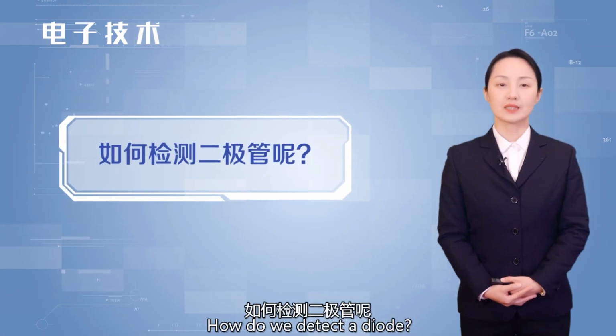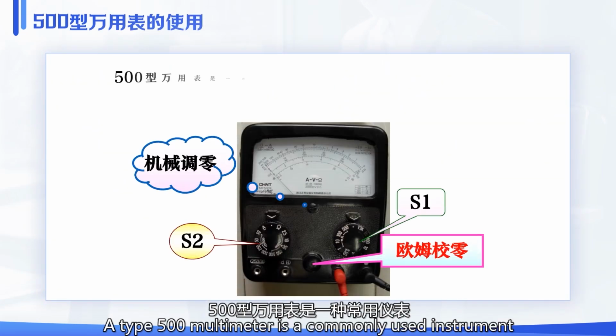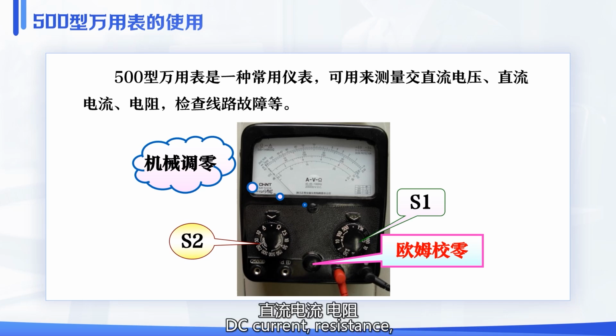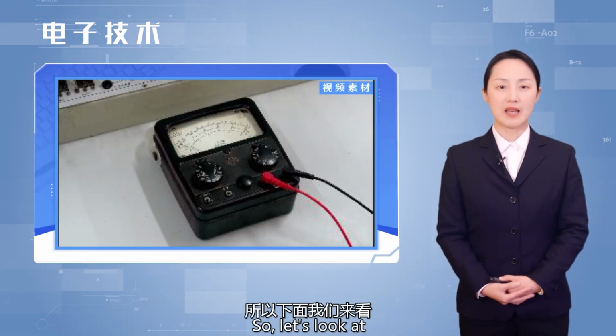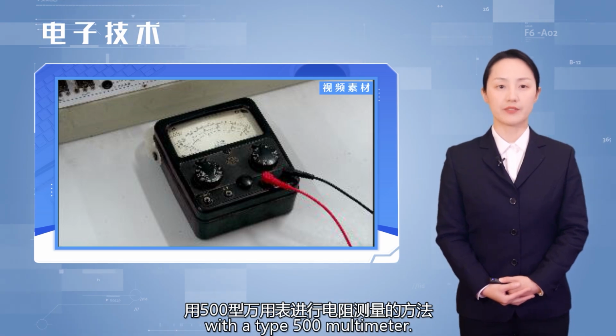How do we detect a diode? We need to use a multimeter. A Type 500 multimeter is a commonly used instrument that can be used to detect AC and DC voltage, DC current, resistance, and to check for circuit faults, etc. When detecting a diode, we need to use the ohm-meter range of the multimeter. So, let's look at the method of measuring resistance with a Type 500 multimeter.